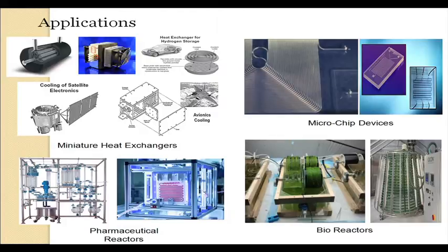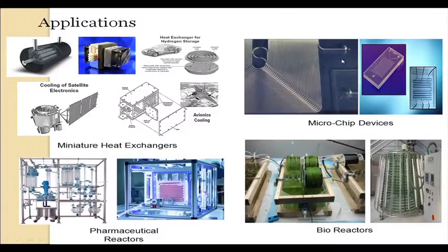But in these cases, the bulk of cooling occurs by phase transfer, and so a greater amount of cooling has to occur by phase transfer. Naturally, two-phase flow, a liquid and a vapor flow, occurs in these applications. So, unless we understand the distributions or the typical characteristics of two-phase flow, we cannot go for an efficient cooling system. So, this is one part of the application